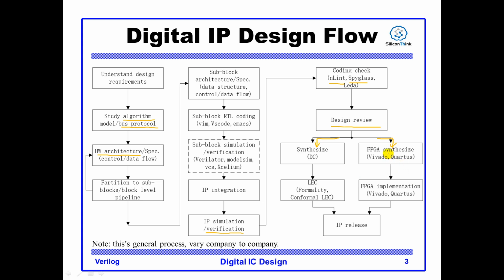And for the FPGA emulation thread, we will synthesize the RTL code using FPGA tools and implement it on the FPGA platform. And we will run the design on a real FPGA device. And in this step, we will co-work with the software engineers and realize all the functions.